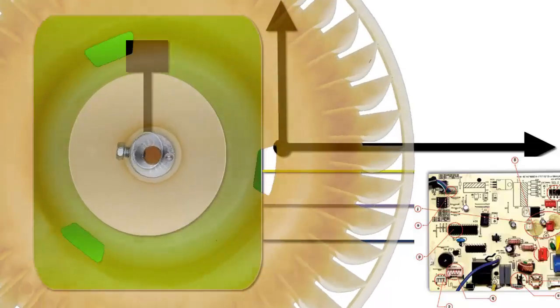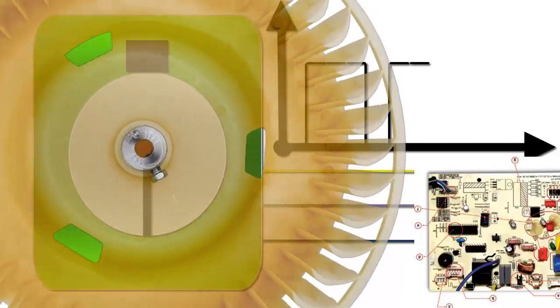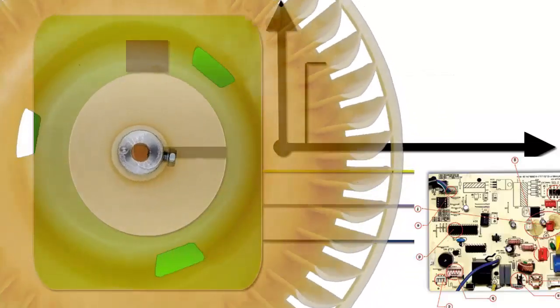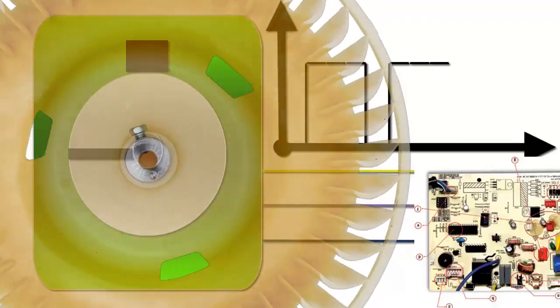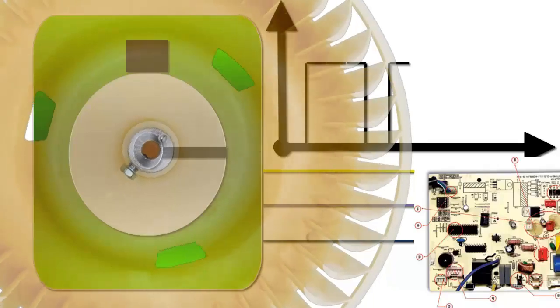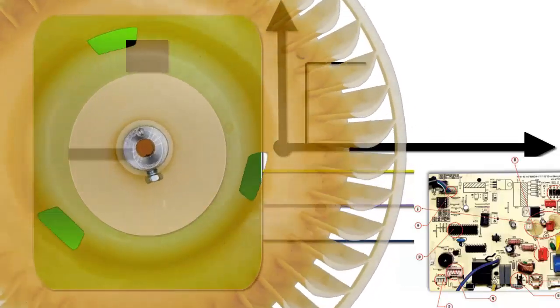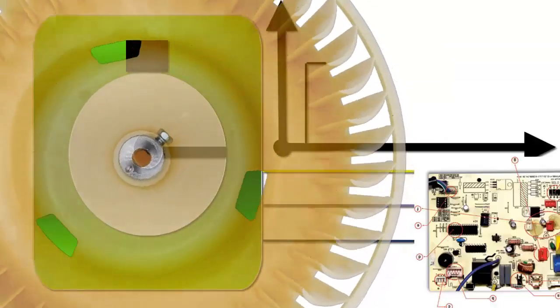In some Carrier units, the E8 code may also indicate failures in the outdoor unit fan. For brands like Bosch, York, and Carrier, the F5 code refers to problems with the outdoor unit fan, while in Midea models, F5 may indicate issues with the condenser fan.